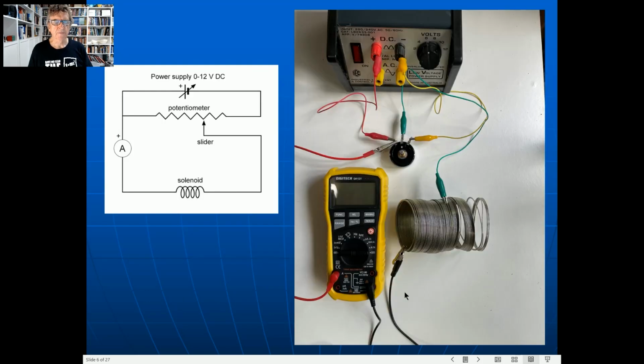Okay, let's move on. So here's the setup that I used for this prac. There's the circuit diagram again. So there's the power supply. Look, I've got it set on about 6 volts. Now it goes into one side of the potentiometer, and then the current goes all the way around here. So it goes in the ammeter, out of the ammeter, through the slinky. Now I'd have to have that pulled apart. I haven't for the photo, but if those coils are touching, they're going to short circuit. So instead of having 50 turns, it might appear to only be 20.